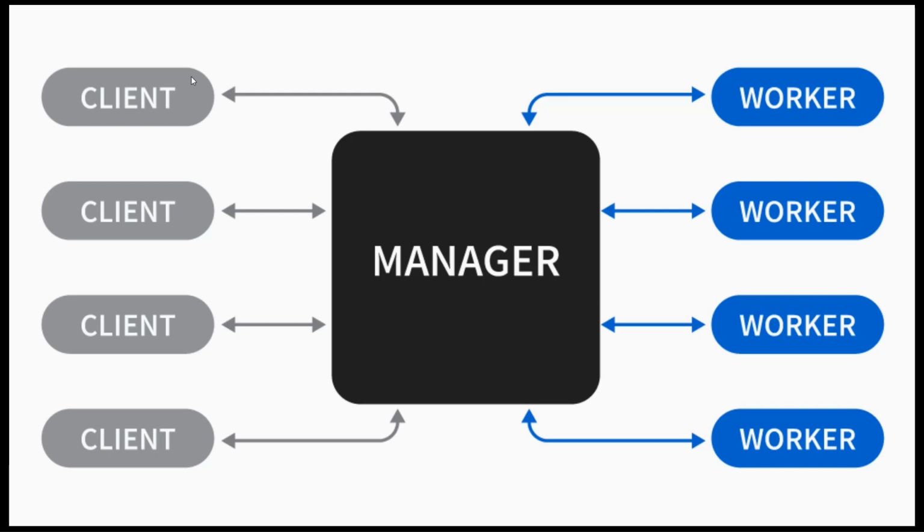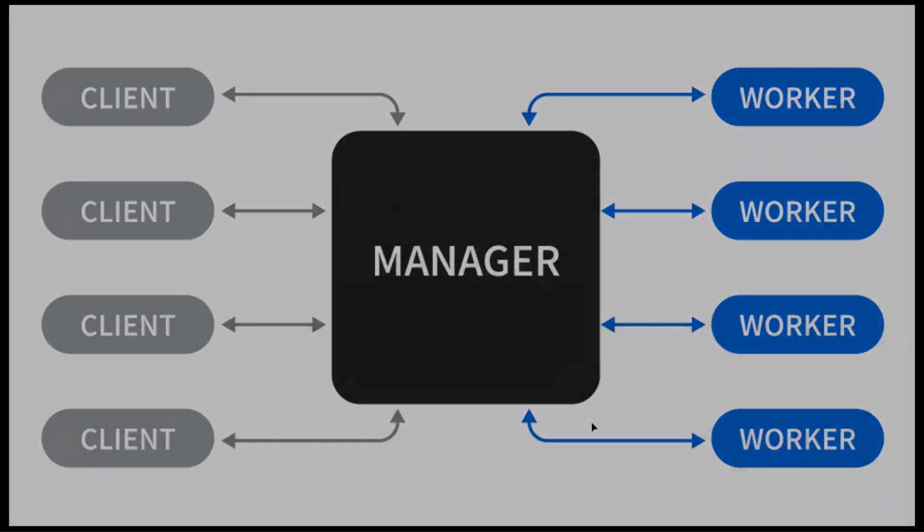Network rendering consists of three roles: the clients, the manager, and the workers. The KeyShot client application communicates internally with the manager service and assigns the job tasks to the available workers. The workers are the machines that you've added to your network. You can have both CPU and GPU workers, but be aware that adding slower machines can sometimes decrease total render times due to increased load balancing and network latency.